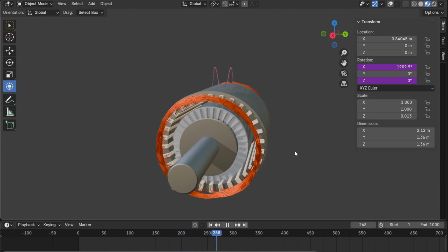Well, if our stator field is weaker, that means we're going to have less flux. If we have less flux, we're going to have less current in the rotor. Now, this is all going to be temporary. We're thinking about the state of things as they develop, right? This isn't what happens in the end, but for right now, we have less rotor current. All right. And that means the entire magnetic fields in this motor will be reduced, they'll be less strong.